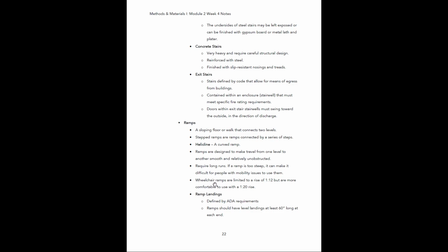That's what you need when doing wheelchair ramps for accessibility. And they even say a more comfortable one to use, if you can, is a 1/20. So instead of 36 feet, you're now looking at 60 feet to move upward just 3 feet in the air. So they have a huge footprint.